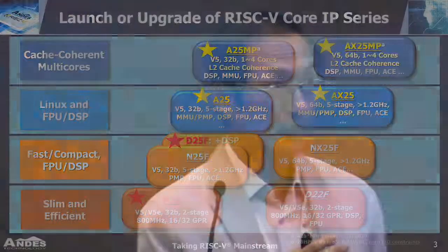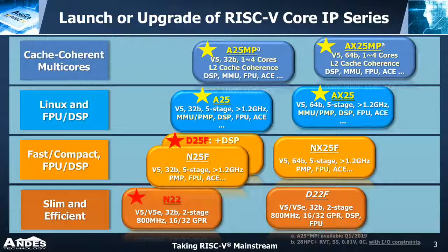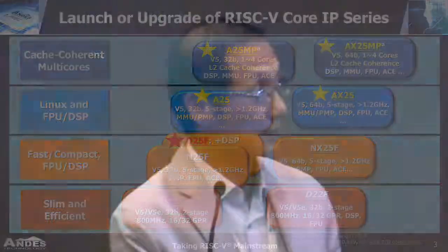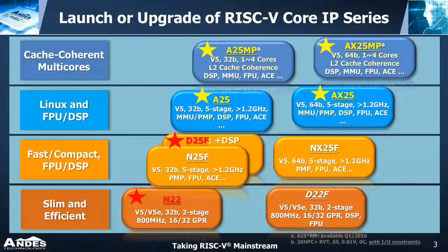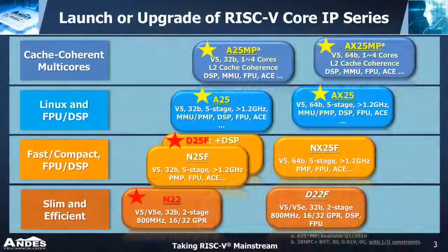But we also have subsystem IP, which we sometimes call platform IP. That's the IP part. I will focus more on the RISC-V cores. RISC-V has some significant characteristics. For example, it's simple, it is modularized, and it allows you to add your own extensions or customized instructions.